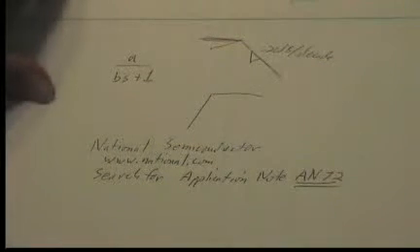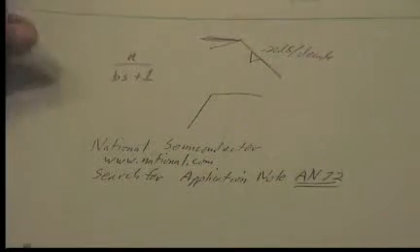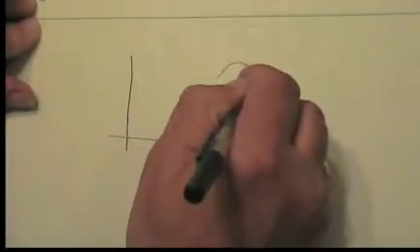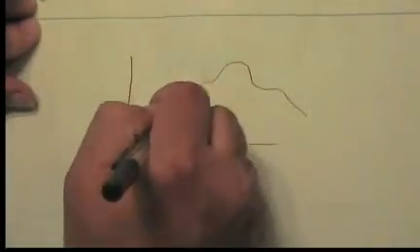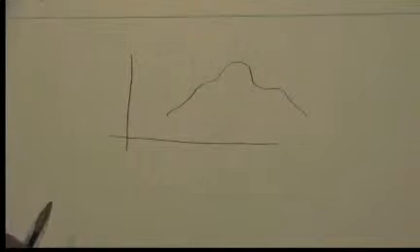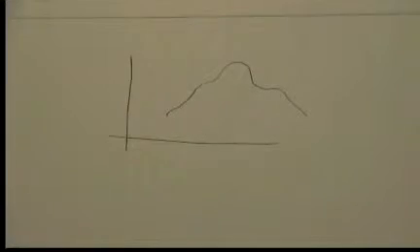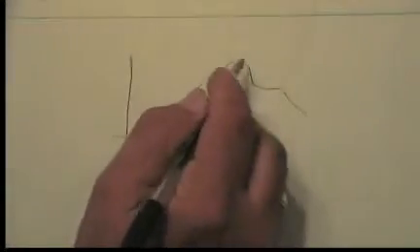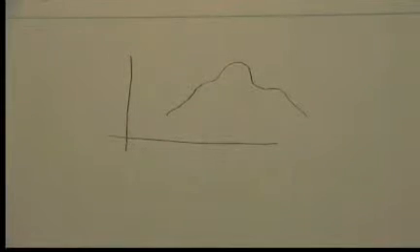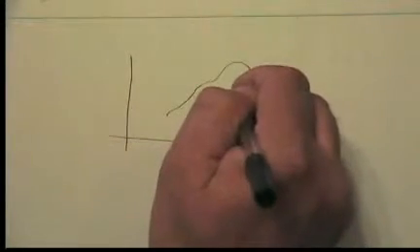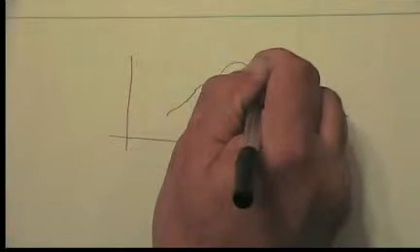So let's suppose that I'm trying to compensate the frequency response that I gave you for those Bud earphones, and just as an approximation, we'll say that the shape was something like this. That's very rough. In order to compensate for this, I'd like to get a circuit whose overall frequency response is basically the inverse of this. And I'm going to draw it as a series of straight lines as an approximation. So I'd say, well, to compensate for this, let's say I'm going to have something that goes like this. It's going to rise in frequency to about here.